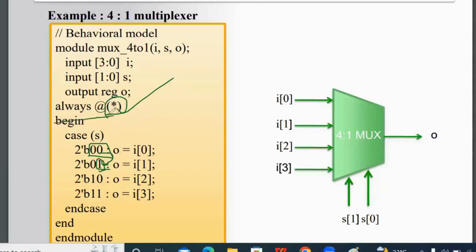So that is what always @(*) does: star means by default it will include all the inputs. Here we can put 2 inputs easily, but at a project level or protocol level there will be many inputs, control signals, data signals, enable signals, and we might miss some. That's why if we simply put star, by default it will take everything.